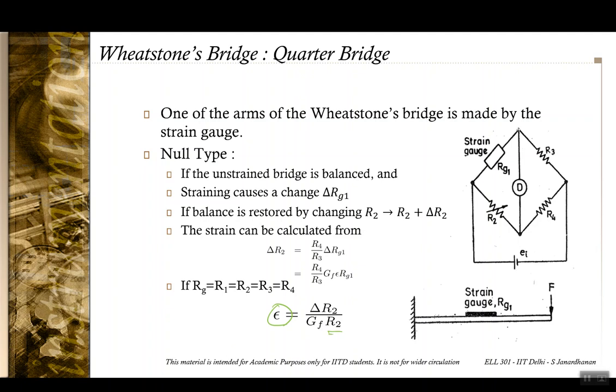This is under the assumption that all the resistances in the unstrained case are of equal magnitude. If not, you just add the factor of R3 by R4 to this. But that rarely matters.